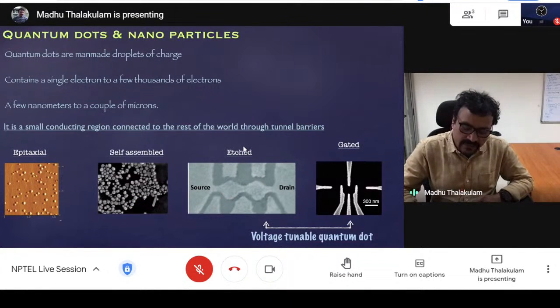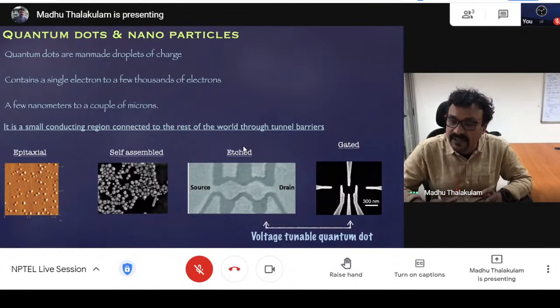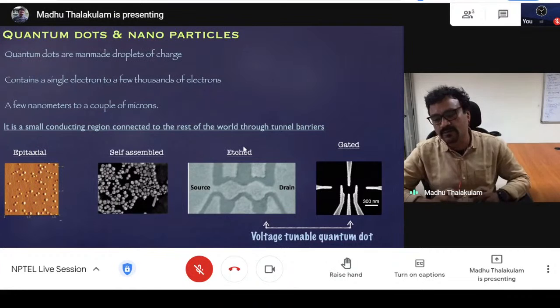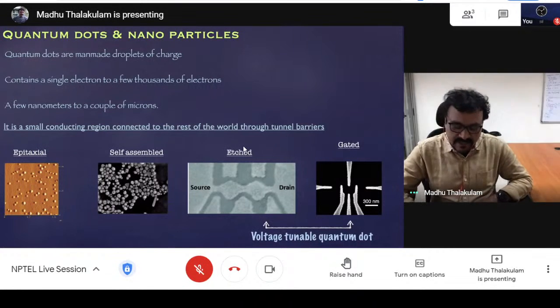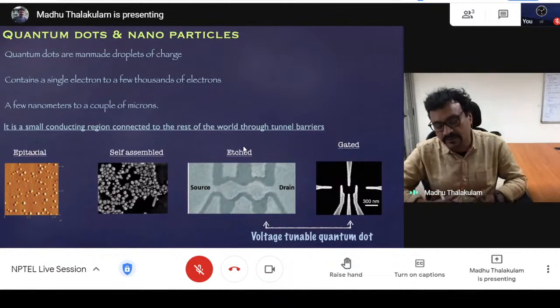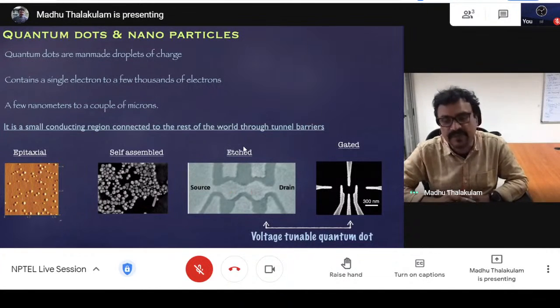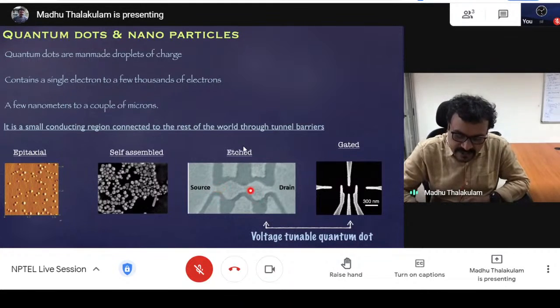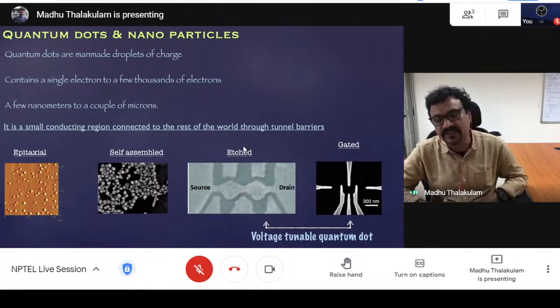And the third and fourth here are realized on large material by limiting the mobility or motion of the electrons. In the first case here, you have etched regions which are confining the electrons. So these are the quantum dots here. And the small neck-shaped regions you can think of as the weak links to connect to the source and drain and between each quantum dot.